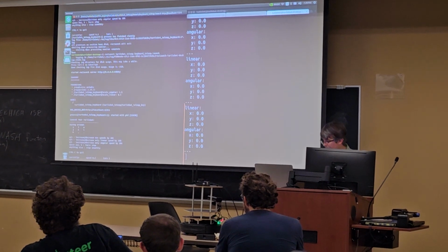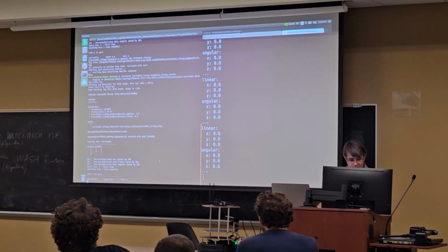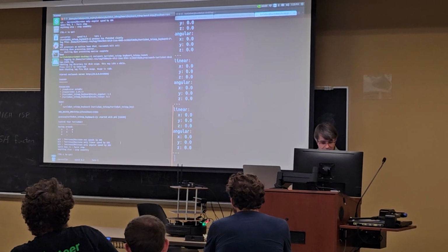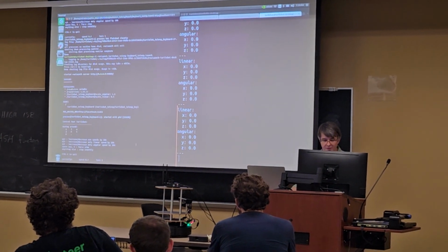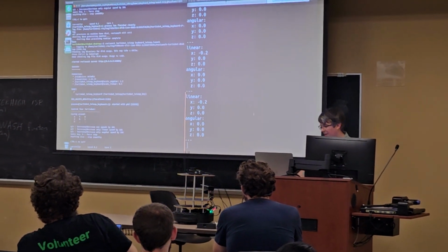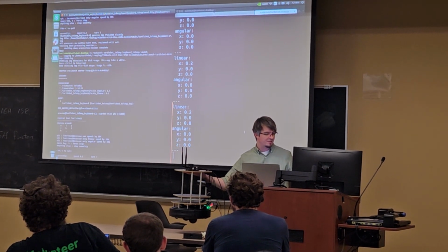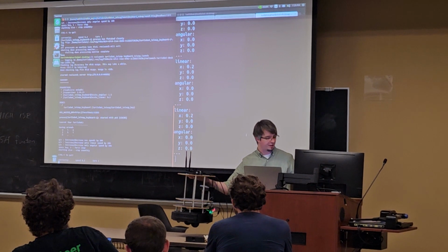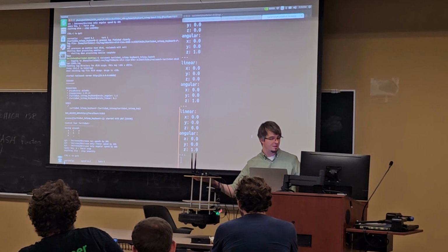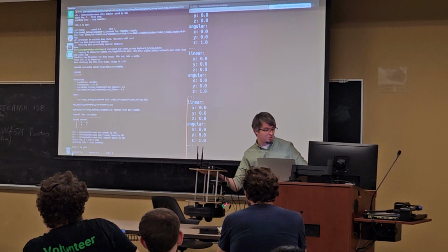Okay, so now if I publish something to it, we should see, there we go. So I'm just telling it to go along the x axis of velocity. So you'll see, actually, there we go. It's commanding 0.2 meters per second as a linear velocity. And if I now tell it to turn to the left, we'll see along the z-axis a rotational velocity published.